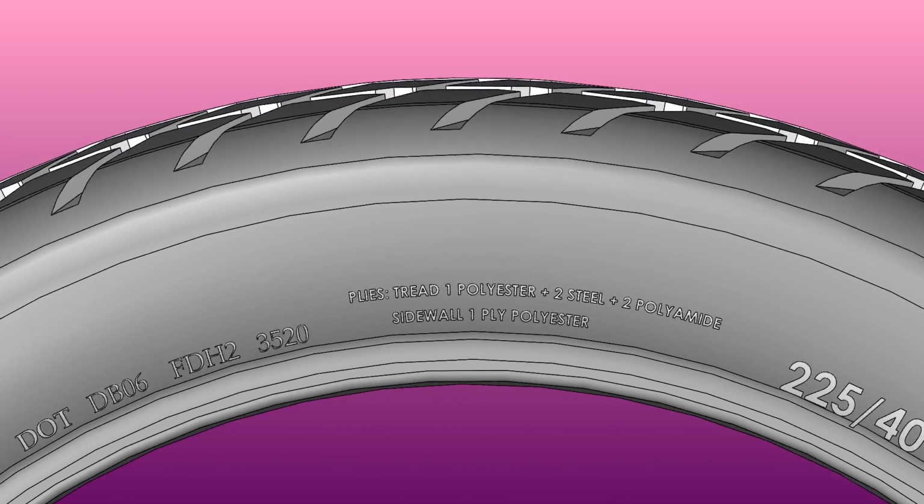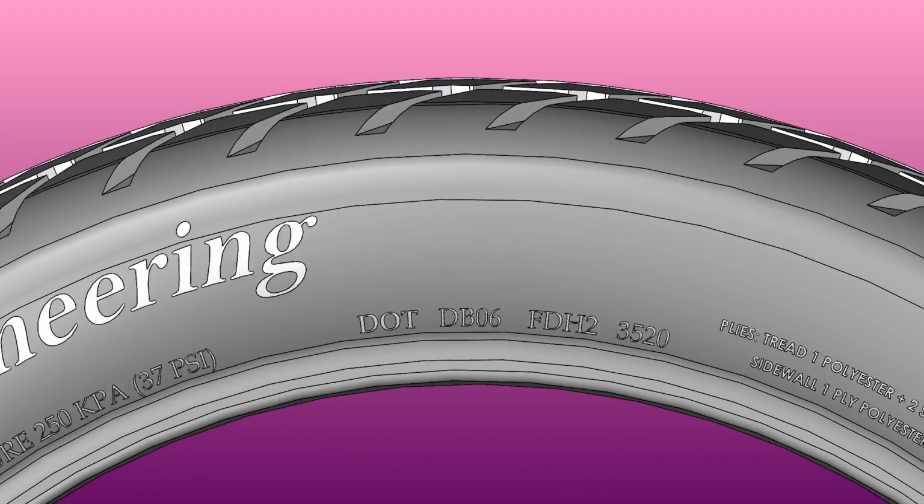On tires, you can find some digits and letters after the letters DOT, which represent the Department of Transportation of the United States. These digits and letters are known as the tire identification number, which gives you information about the tire factory, size, type, and the last 4 digits show the manufacturing date. The first 2 digits indicate which week of the year, and the next 2 digits indicate the year of production. Like 3520, that shows the tire was produced in the 35th week of the year 2020.